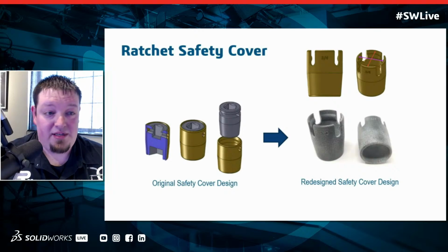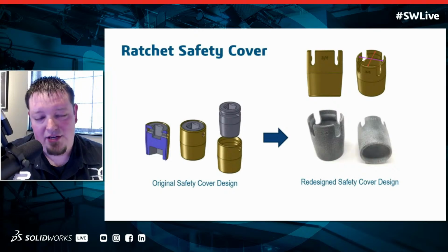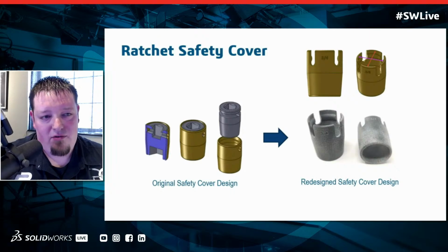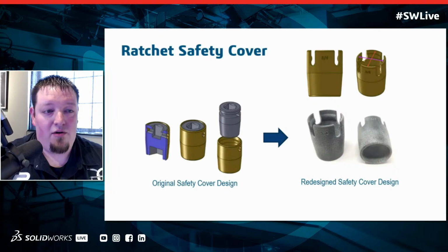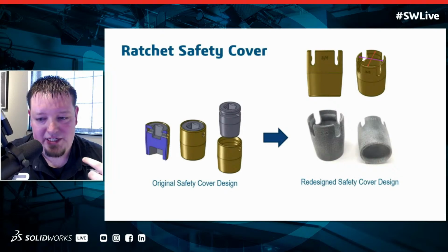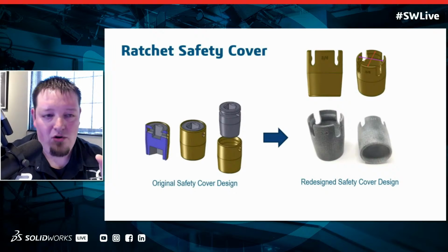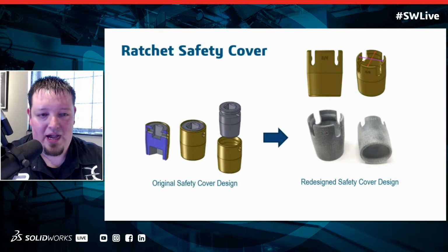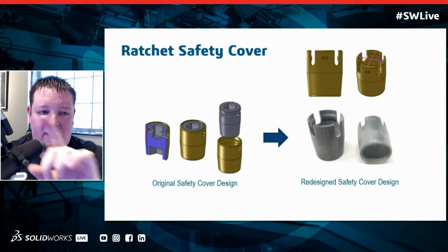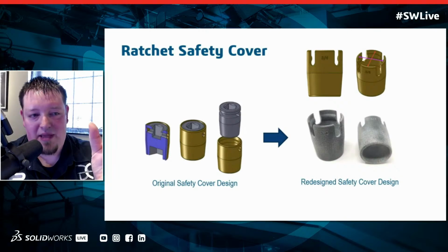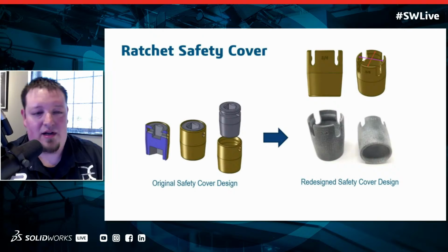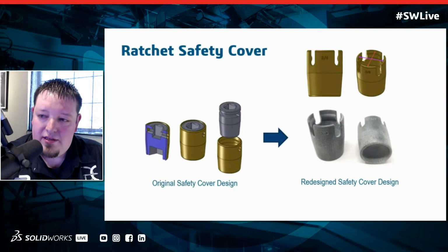Now we originally just printed the design that they had, and the issue is our nylon doesn't have quite the same flexibility or elongation at break that a Delrin has. And so we would actually split these when we would go to press them together. So what we did is we created a rosebud kind of design. Instead of having a solid detent all the way around, we put it on these petals so that as you push the socket in, it petals open and then snaps back shut again. Another thing that's really cool is we can print the socket size on the outside.